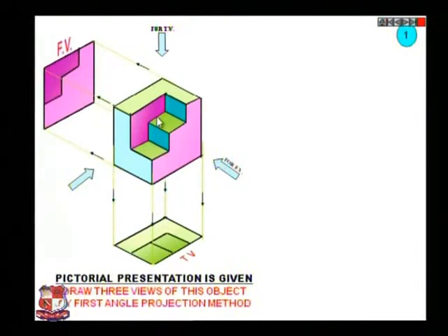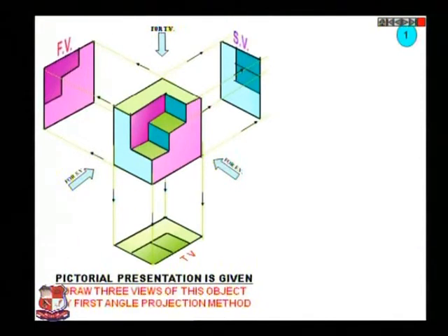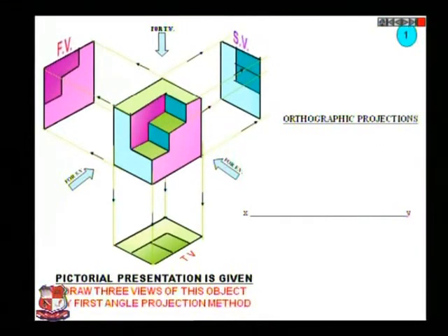And about its side view, if you look from this side, this L shape would appear. Draw projection line from here. Or if you take a photograph from this side, it would appear as shown over here. L shape and 2 rectangles. So these are the 3 views of this given object, that is called as side view, and this is orthographic projections. It could be drawn like this.